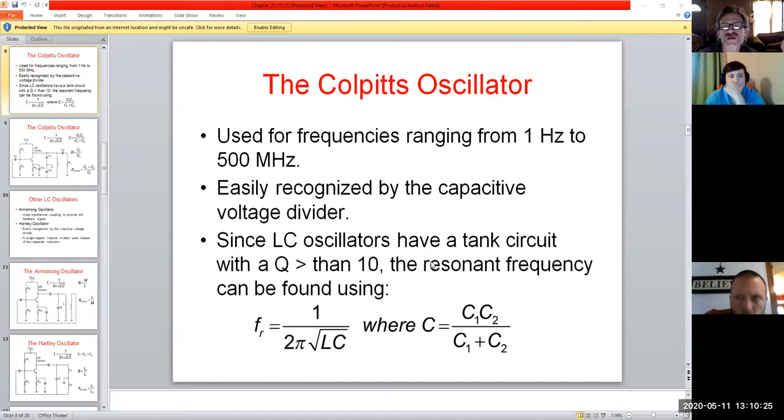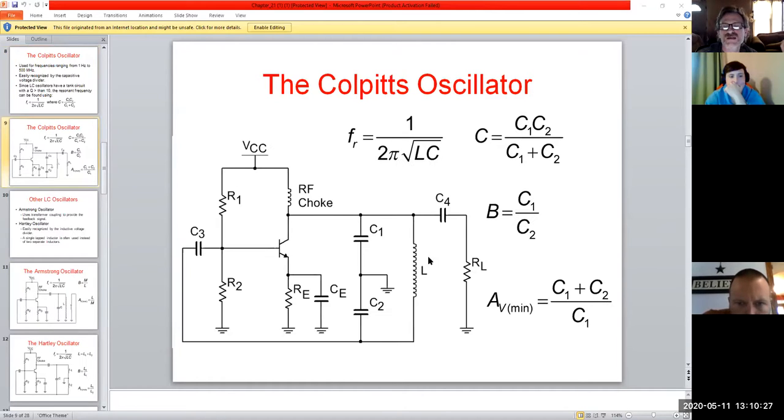But they have a tank circuit, and a tank circuit is basically an LC circuit, if you will. If you remember the way an inductor and capacitor work, if we look at them together in a parallel configuration, you're going with the two phase oppositions, trying to balance each other out, if you will, to swing into the middle and provide us with a fairly stable output.